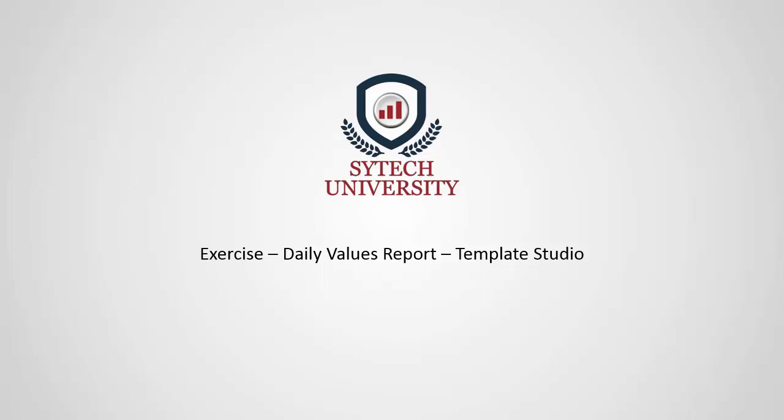In this video, we'll demonstrate creating a report that shows hourly values on daily worksheets inside monthly workbooks from process history. We'll create the report in the Template Studio, then we'll validate it in preview mode, then we'll test it out and backfill some data, and finally deploy the report to update automatically using the scheduler.